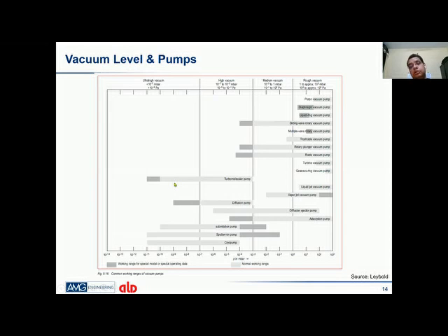But when we have to use turbomolecular pumps to generate a vacuum of minus 7 and minus 8, other things also become very critical, like what the vessel is, what inside cleanness we get from the vessel, and what material the vessel is manufactured from. I'll try to show why these things become more and more critical when we are using the turbomolecular pump. At the industry level, most of the time we use diffusion pumps. And if it goes up to a very critical application where a very high quality part is required, like in nuclear or medical applications, we see turbomolecular pumps being used.